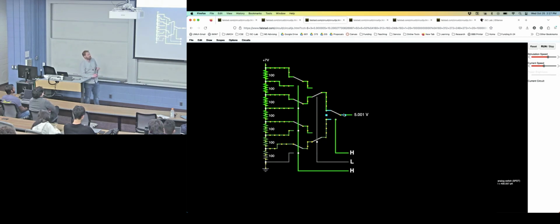What other questions do you have? Yeah. Wouldn't it take up a lot of space? Yeah, every binary value you want, you have to have a resistor for. So this is great for teaching examples. It's also very fast. You get the answer in 1 clock cycle, so that's good. But the ultimate utility of it is going to be low, in the sense that you can't get a lot of bits out for the cost and space it's going to take. But it's fast. What's another problem on the output that we have to worry about?